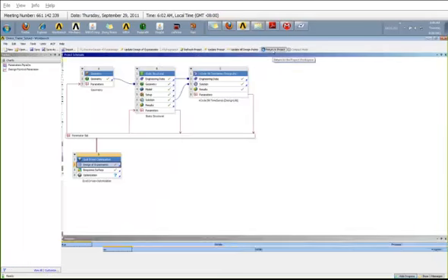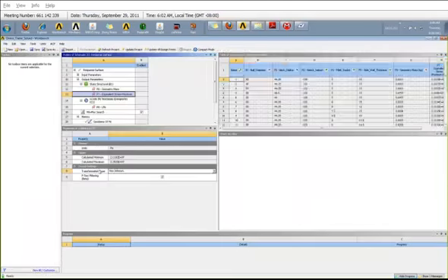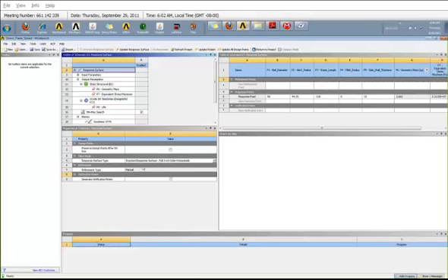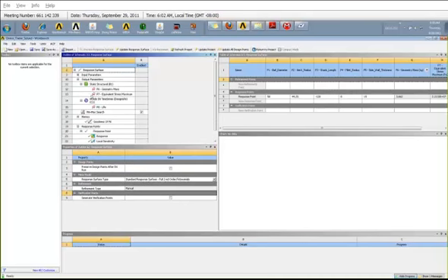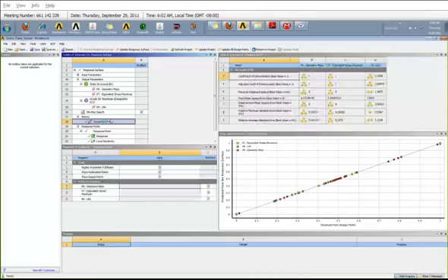Now let's return to the project here. Now go to the response surface. So in the response surface, I'm going to go with the default one, which is a standard response surface, full second order polynomial. For each output variable, it creates a function of the input variables, and the function is a second order polynomial. Since we are doing some kind of curve fitting or surface fitting, it is appropriate to look at the goodness of the fit. The coefficient of determination will tell you how well the variability of the input parameters is captured.